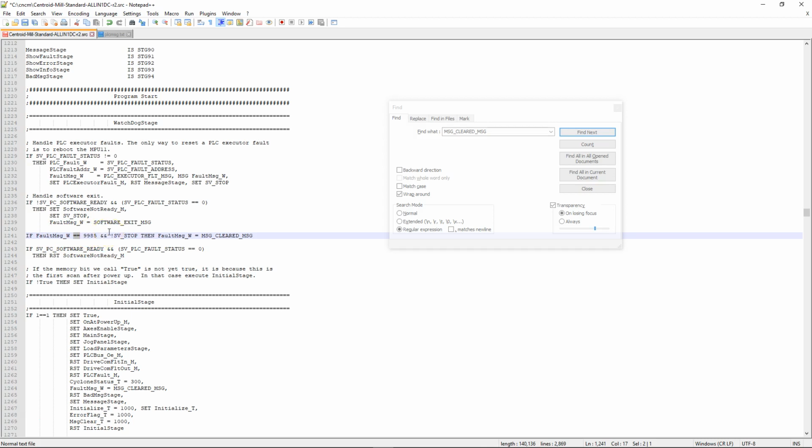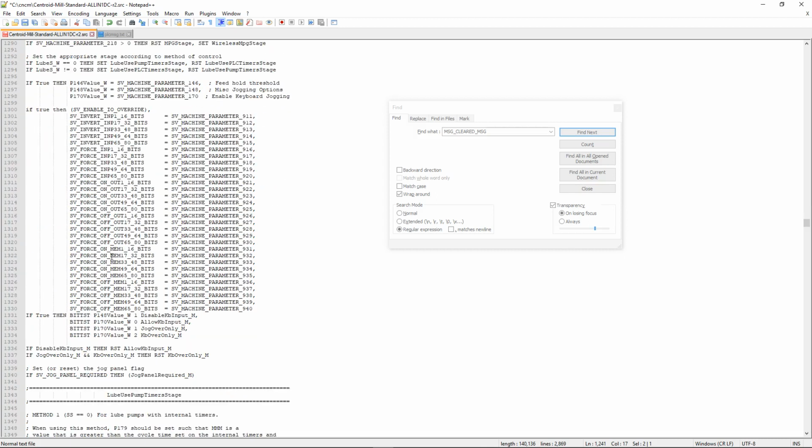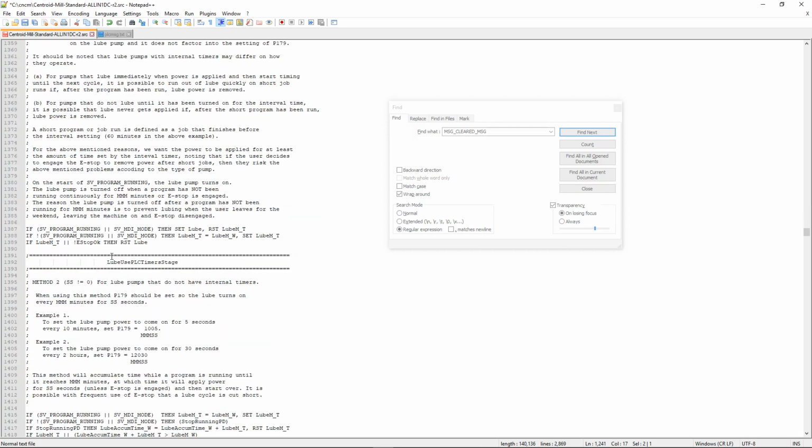Now, we talked about the logic and. There's also a logic or. Logic or is two parallel lines together. Let me see if I can find that for you. Okay, right here. We've got these two conditions and it says this system variable or this system variable. In this part right here, you can see that these two conditions are inside these parentheses. Quite honestly, on this one, it doesn't really need it because that's the only part of the condition on there. So if you left the parentheses out, it would still behave the same.